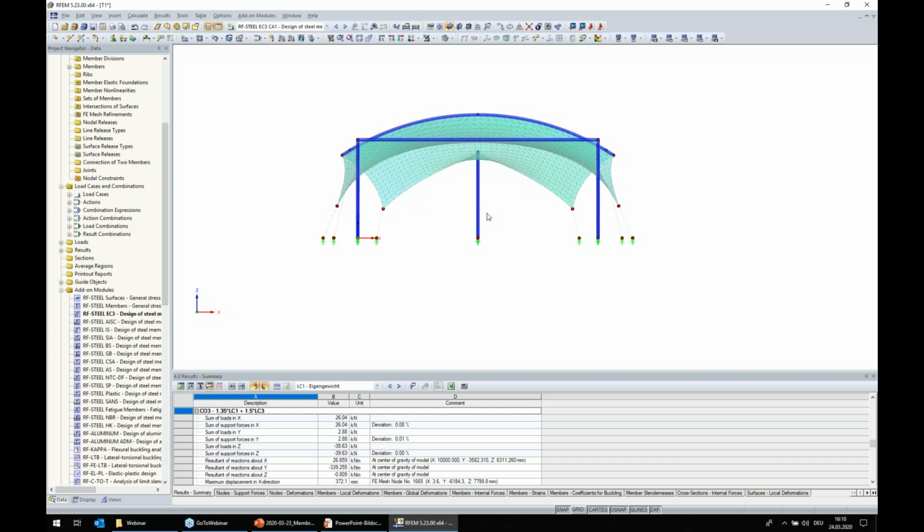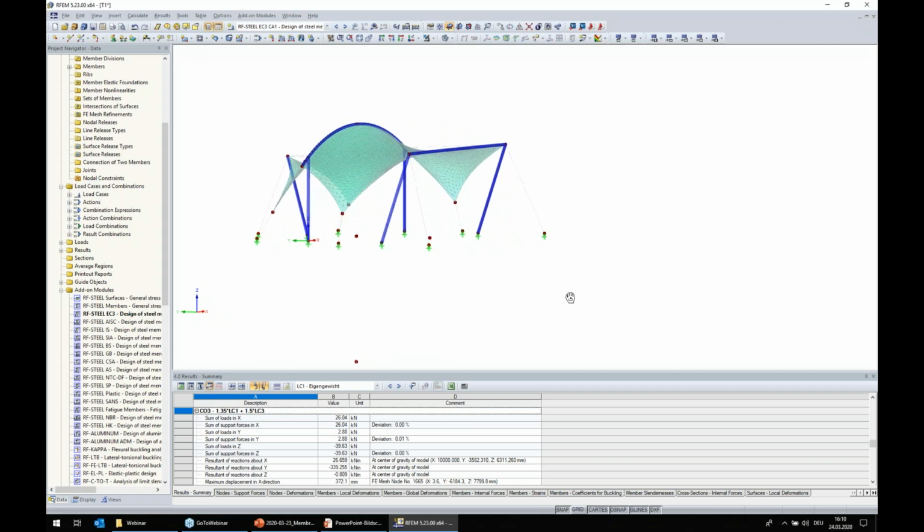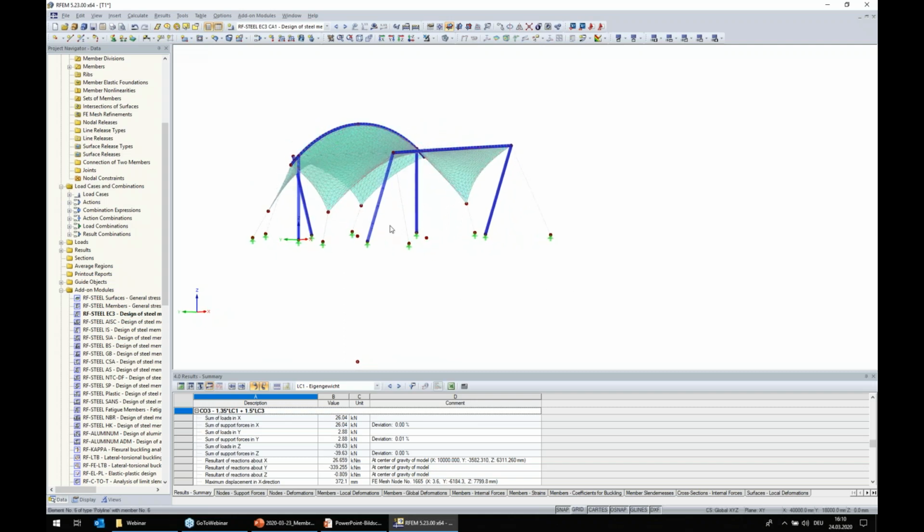But imagine the event manager decides that the people below these roofs get something to sit on, a sitting construction. Then the wind cannot run through the model and has a different interaction on membrane or members than we considered now.